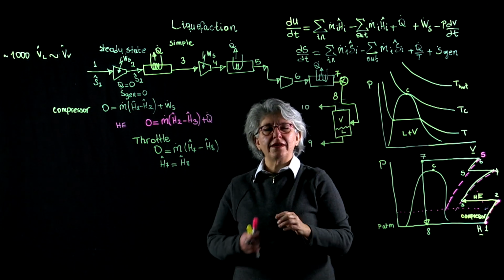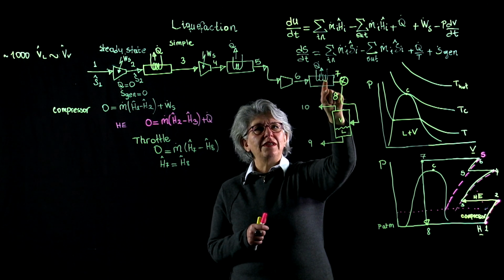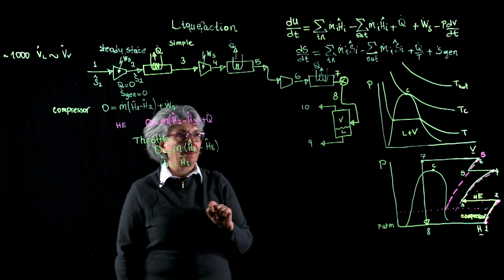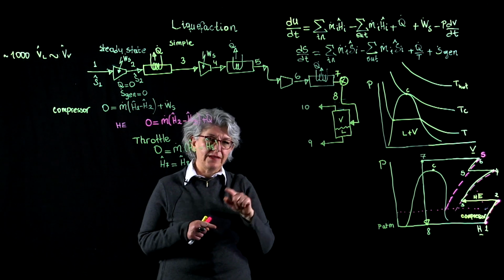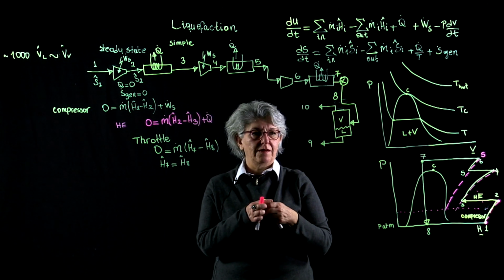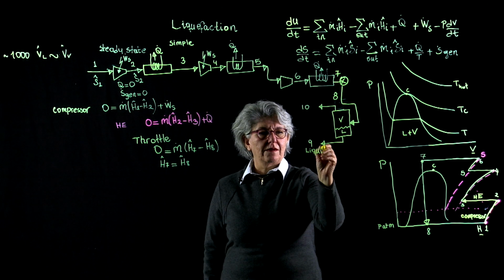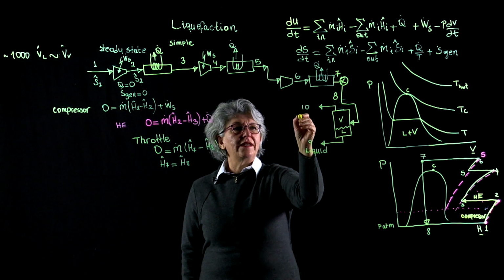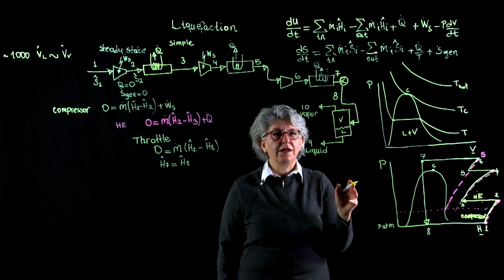So it is a very common practice of using this stream to exchange heat here, sometimes here and here also. But now this simple liquefaction process is inefficient in the sense that part of the product is being discarded as vapor, after, of course, we have done the heat exchange, right?